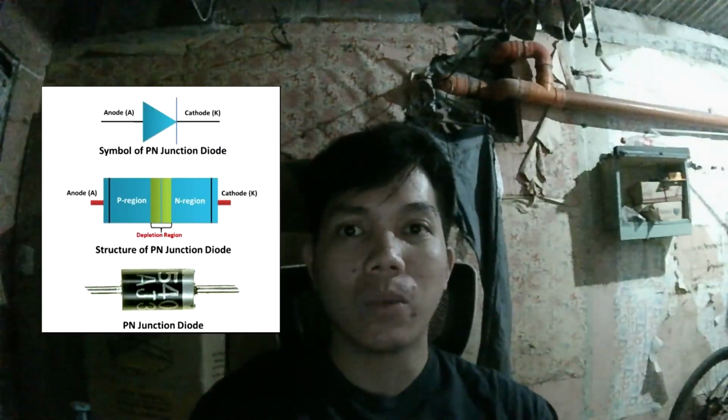Nowadays, the most popular type of diode is a semiconductor diode, which is a crystalline piece of semiconductor material with a p-n junction attached to two electrical terminals. It has a current-voltage characteristic that is exponential. The first semiconductor-based electronic devices were semiconductor diodes. German physicist Ferdinand Braun made the discovery of asymmetric electrical conduction at the contact between a crystalline mineral and a metal in 1874. Although germanium and gallium arsenide are other semiconductors, silicon still makes up the majority of diodes today.